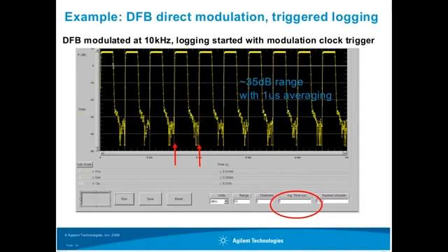So this is the case. Even with 1 microsecond averaging time, we're getting down past 30 dB. Well, even more than that, actually, close to 40, because we're starting out at, in this case, a power fairly close to 10 dBm, actually. All right, but at some point, it kind of turns into the noise. So I would even correct that to be more about 40 dB.